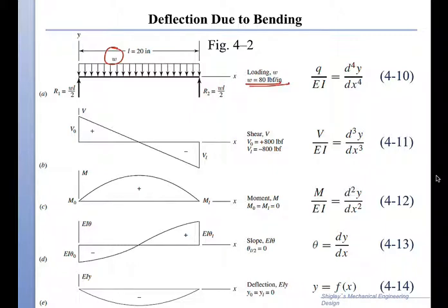pound force per inch, and the reactions, of course, once we multiply W times L, it gives us the total force on this beam, and we split it half on each side. We got the reactions very quickly. So the reactions will be WL over 2 on the two sides. Now this diagram here is